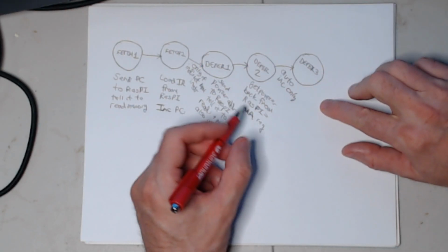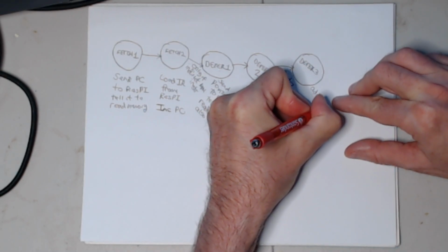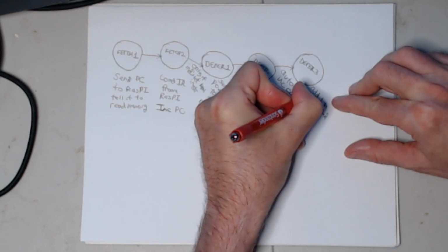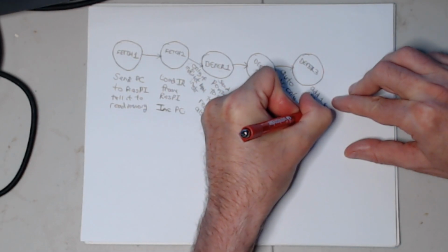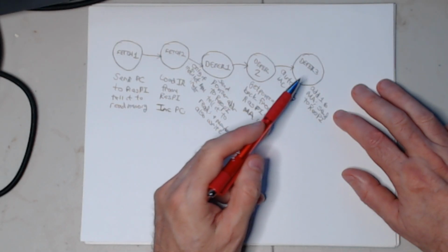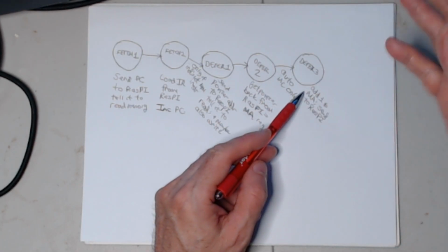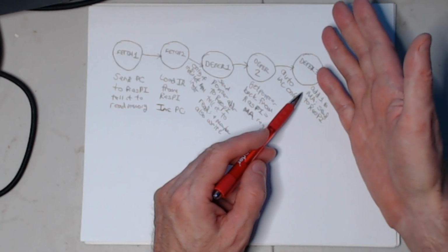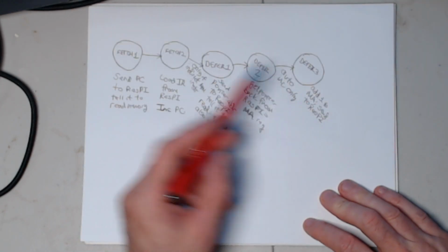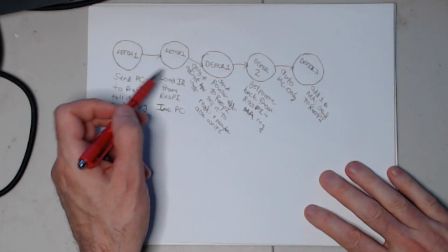And what do we do here? We're going to add 1 to the MA, and send it back to the Raspberry Pi. It's going to add 1 to that memory address register only if it was an auto increment. Now we have, in the memory address register, coincidentally, the incremented value, and the Raspberry Pi is going to store that incremented value back in memory. So if we use that pointer again, it will be incremented for us to work.